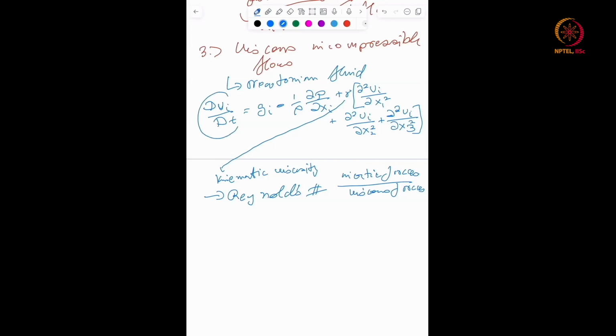Remember, the nonlinear term is contained here. So you can get Stokes flow in the range where the Reynolds number or the inertial effects is negligible. That means essentially very low Reynolds number events, and that is called the Stokes flow. When Reynolds number, which is represented Re, is very small, you can go to the Stokes flow.